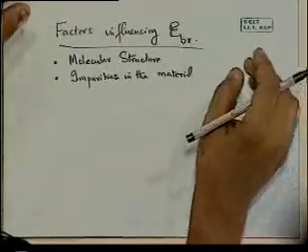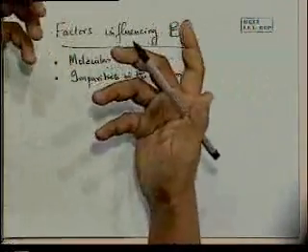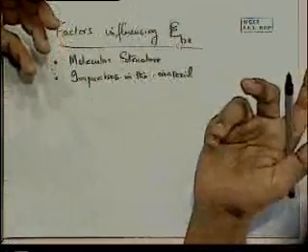If there are certain impurities that can result in charge transport, then once you have high enough field, certain ions or certain metallic impurities start conducting current. And so we see failure much earlier than you would expect for a purer material. So that's a possibility.